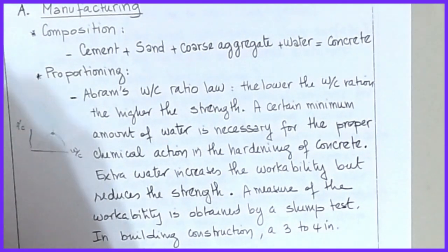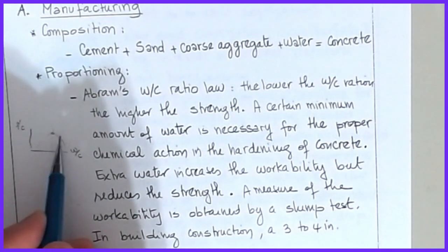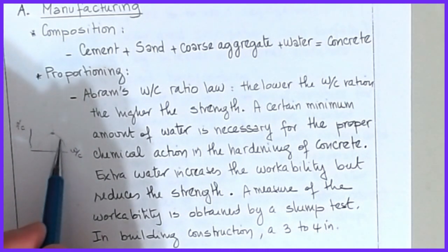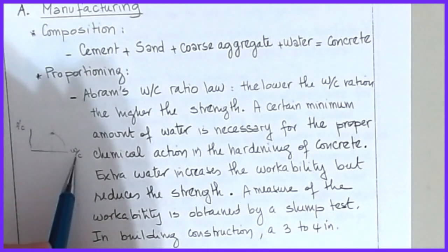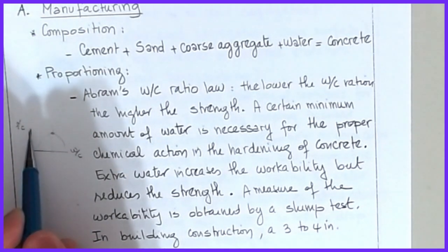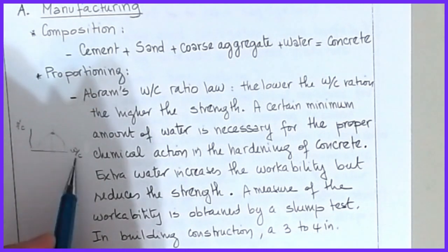This is a bit of a danger because in practice, water improves the workability of a concrete mixture as you're trying to place it into the forms and around all of the rebar. And so you've got to be very, very careful of ways of getting workability without reducing strength. The easiest way is to add water, but when you start getting into more advanced mixes, you can start putting in additives that increase workability without doing that.